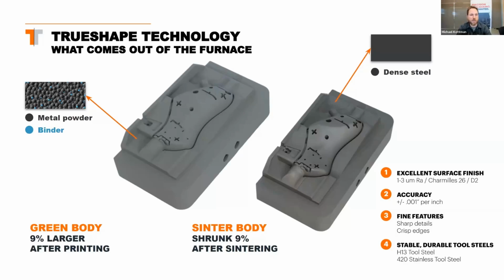We do calibrate our paste on a per lot basis, and we get large lots of paste. Most of our customers are using a single lot of paste for months at a time to print. And we can actually calibrate each batch of paste for its specific shrinkage. That allows us to get this really high resolution, beyond what other processing allows, where you might have a different amount of binder loading in different segments too. So that uniformity carries through here, and that's how we get that accuracy.